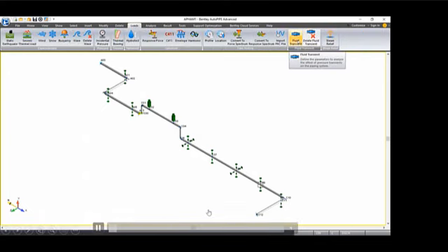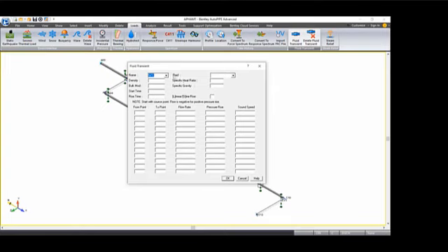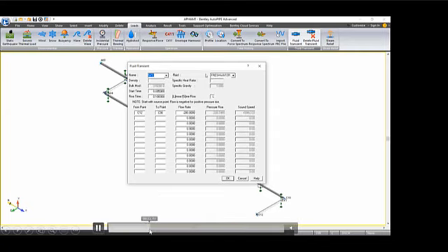You go to loads, remember this is only AutoPIPE Advanced, and in fluid transient you put a name like this. The name is W1, for example. And this is external data that you need to calculate externally. And you choose the type of fluid and the flow rate at points. Which points? Well, it depends on your model.